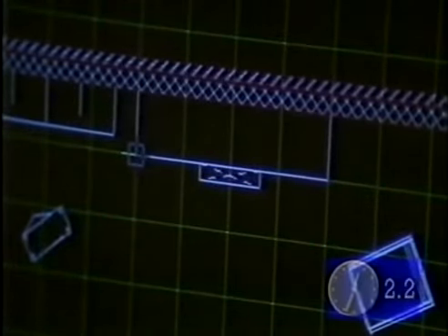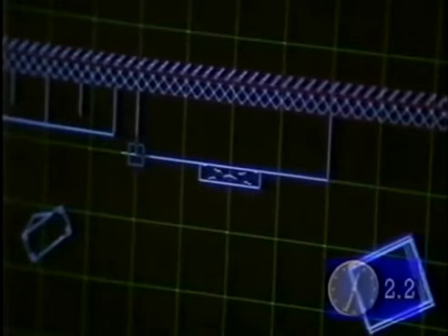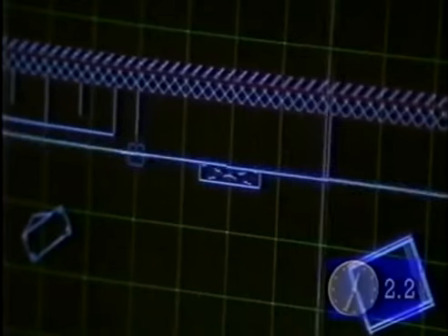we can issue either the Q or actually type in the vectors that we want. I'm going to use the Q option, which allows me, again, just to sketch, to go round the vertices of this face. And R to return me to the start. And there's the hatch. There it is.